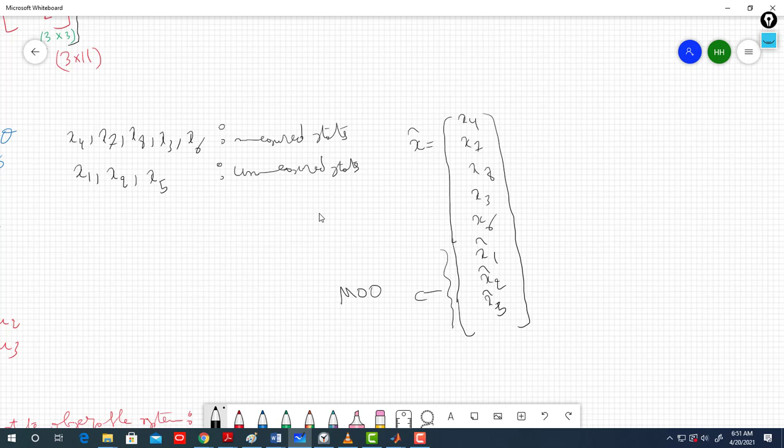Also, it's good practice before building the minimum order observer to check the minimum order observability. As we always do, we check the complete observability, so it's fully observable. In order to design a full order observer, we need to have a minimum order observer. So we can check the minimum order observability before finding the Luenberger gain, or as we call it in the lecture, KE.